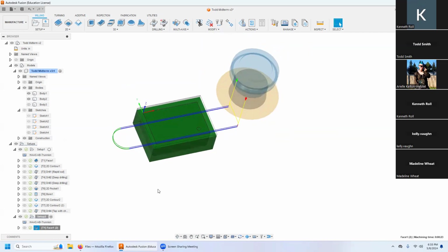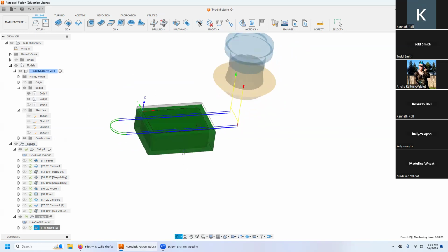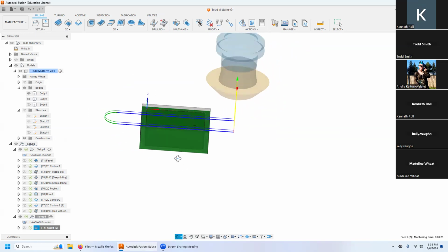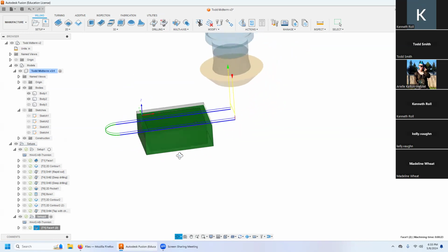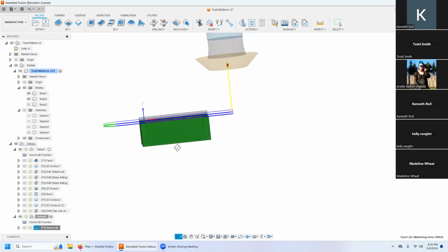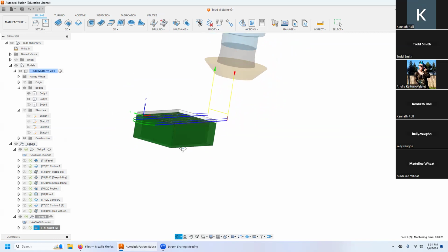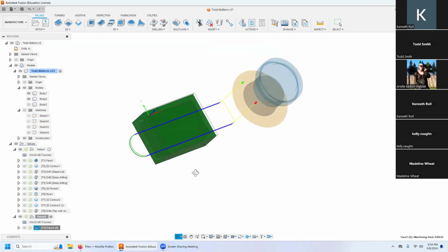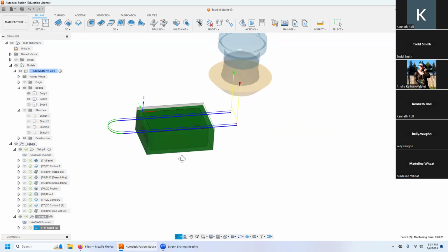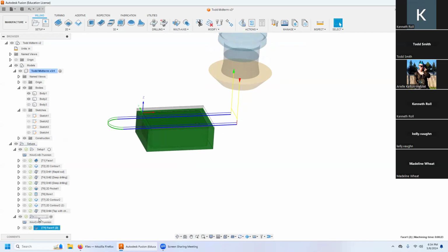That is to say, we're only going to be holding onto the sides with steel jaws. I think we're going to be okay. I don't think it's going to slide, but we'll definitely want to come down and watch the setup person run this to see if it's going to survive or not. We can do something else that's kind of cool here.